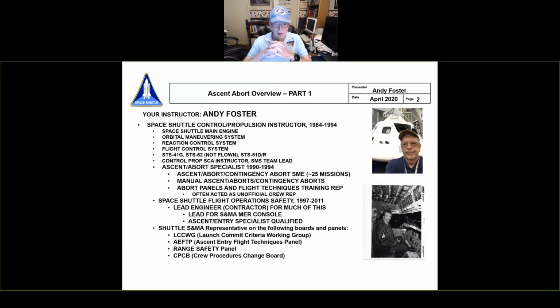So your job was to learn ascents and ascent aborts and contingency aborts. I was the sole contingency abort trainer for about 25 shuttle missions. Part of that job was not only learning them all from a procedure standpoint, which required you to extend yourself and know not just the control propulsion system, but the DPS and the electrical system and the mechanical systems as well, because you had to know all the impacts. But you also got to teach and learn to fly the manual ascents, manual aborts, and contingency aborts. In addition, because of the period that I was there, we were still developing a lot of stuff in the ascent abort arena and especially in the contingency abort arena.